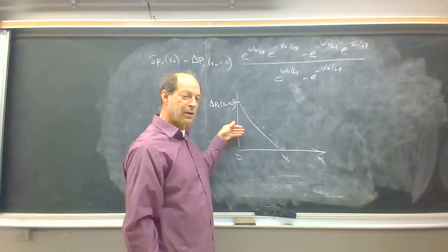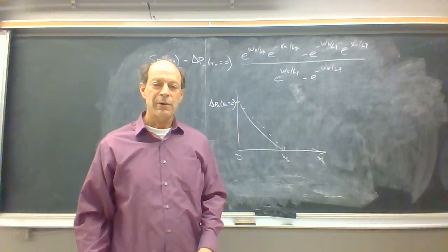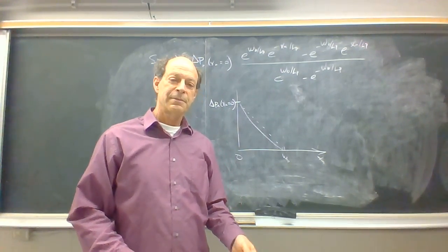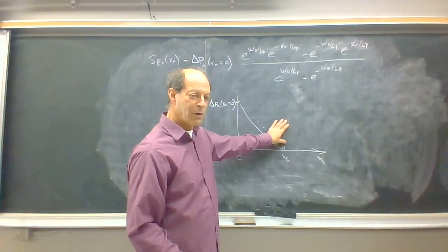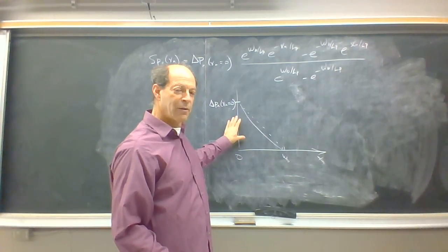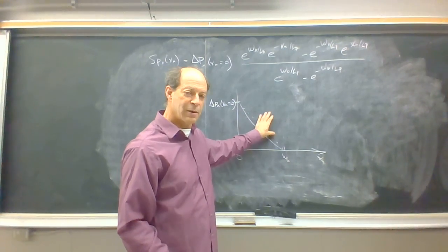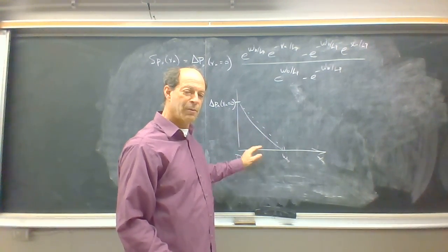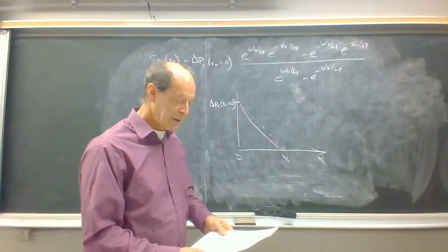Because the current flowing into the base and the current flowing out of the base represents the surviving current, or let's say the surviving current is the output current divided by the input current, but the remaining current, which would be the input current minus the output current, would be the current loss, which would contribute to base current, and we're trying to minimize base current.